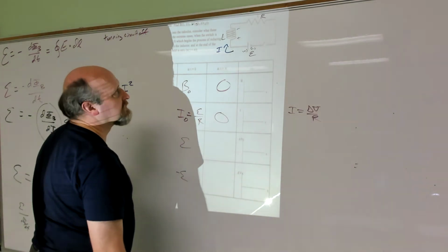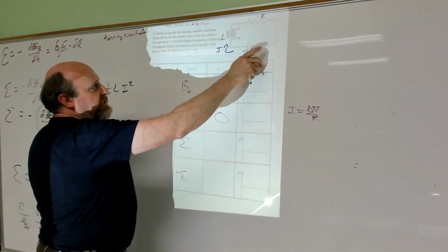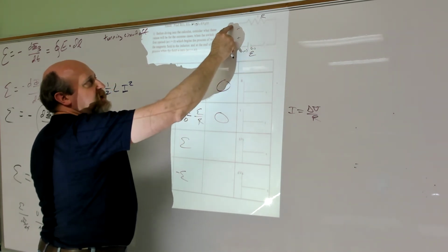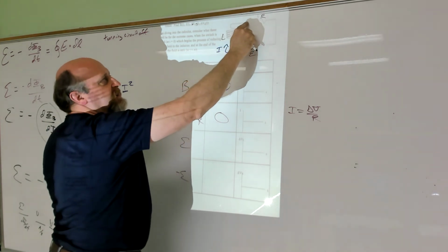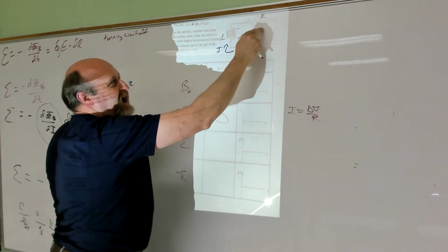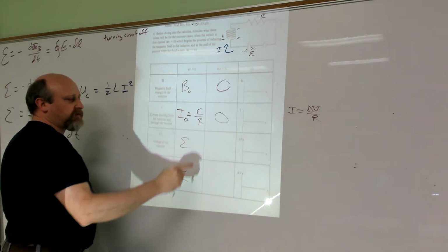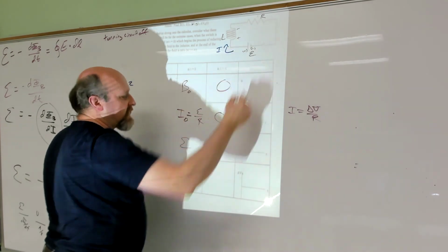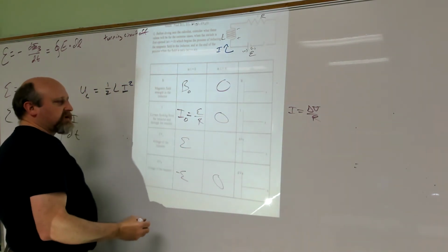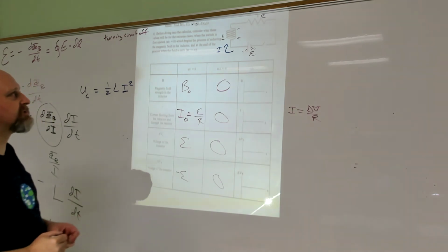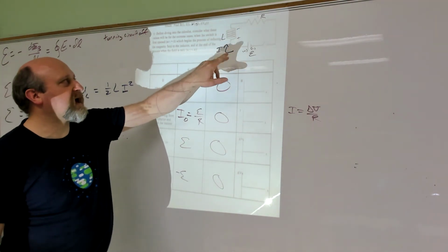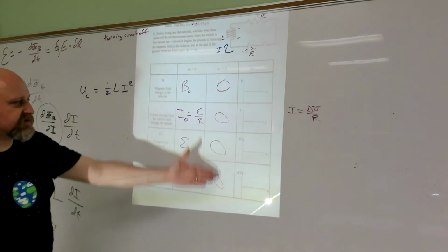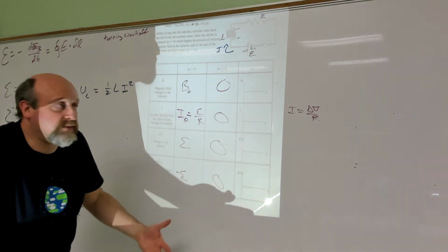All right? So originally, when this was closed, we had this going up in EMF, acting like a bare wire because there was no change in flux going on, and then going down that EMF, it would be I times R, which is why that I is EMF over R. Okay, moving on. However, at infinite time, the current will have died down, and there will be 0 voltage across there, and there'll be 0 voltage across here too. Once I've totally drained all the energy out of that guy, and that magnetic field has died down to nothing, there's no delta V across there anymore. So all these are going to 0 eventually, right? The circuit will turn off completely at the end.